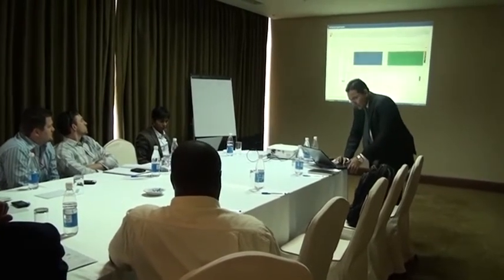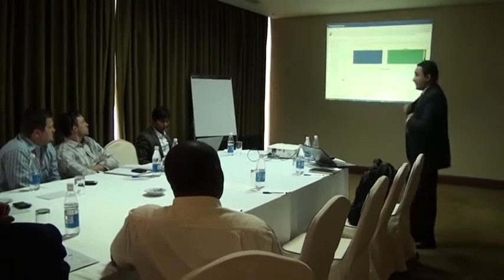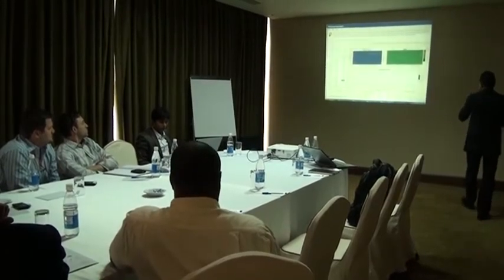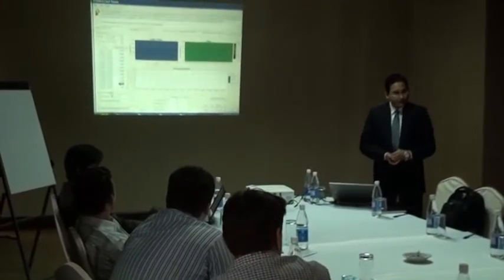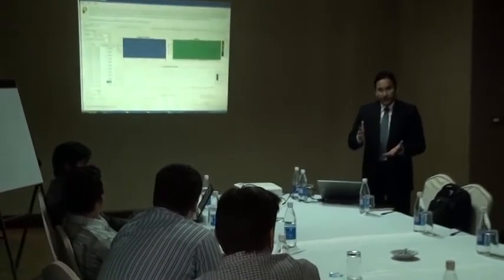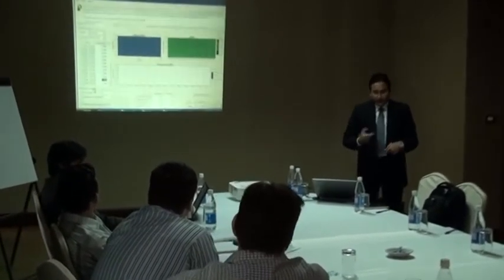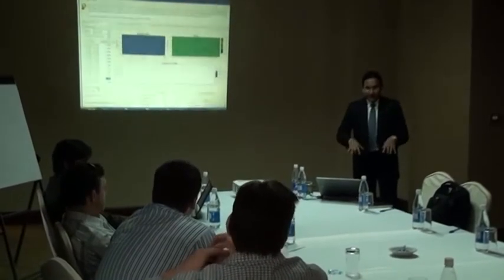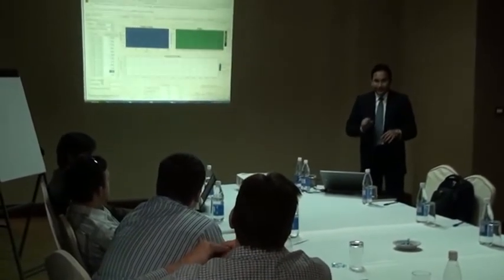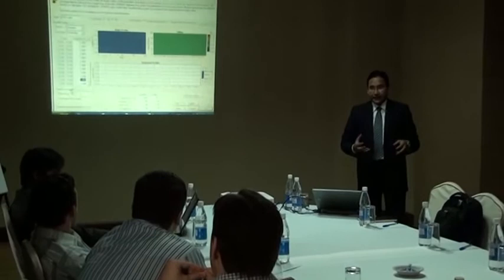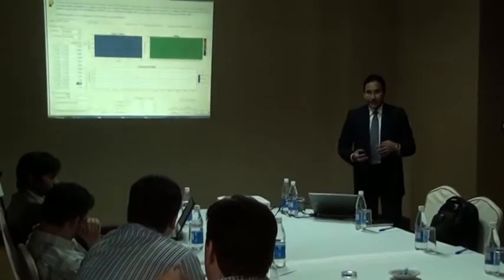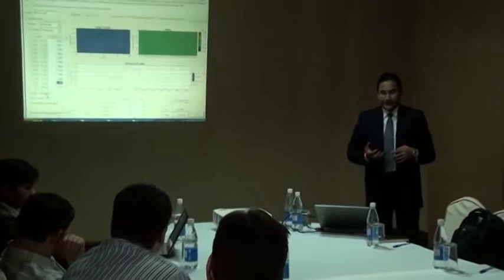All right. Now look at this random variability. Random variability is, do you have any sort of variation that exists in your power requirement at that site? What it means is, let's say for some reason there is day to day variability, because this site is located in a marketplace, and the market happens every alternate day. So during the market day, your TRX utilization goes higher, because a lot of people come to the location, and your power consumption goes higher. So let's say it happens every alternate day.